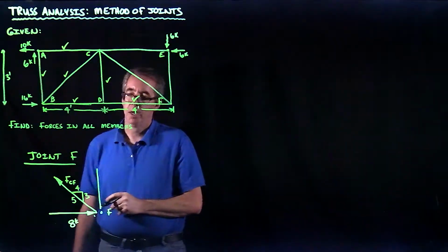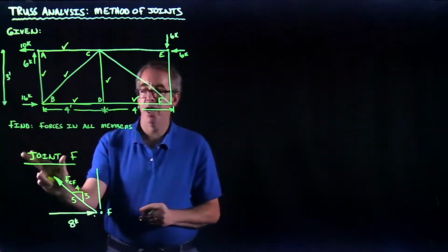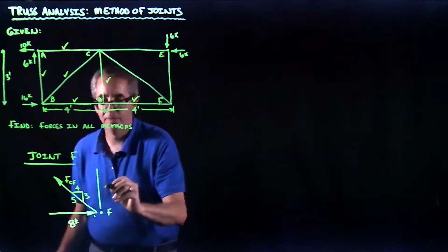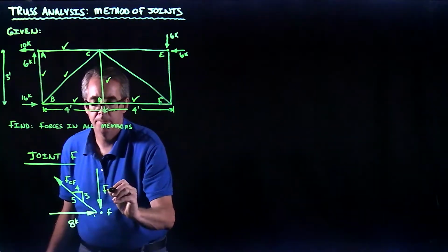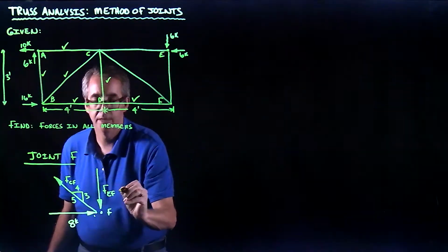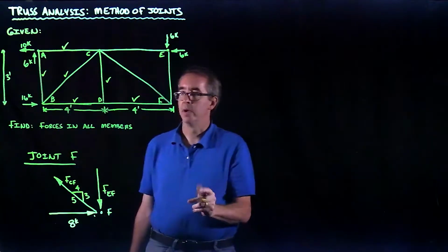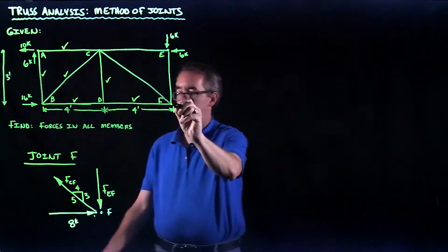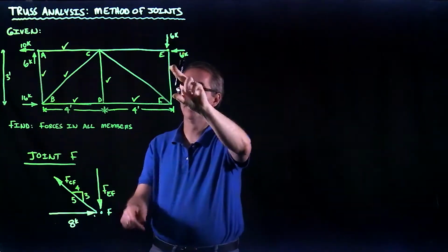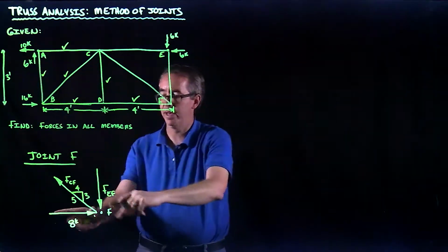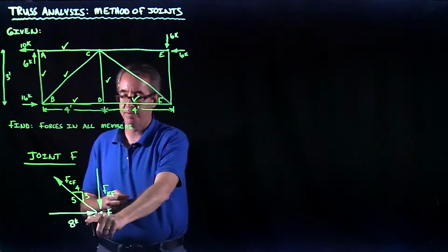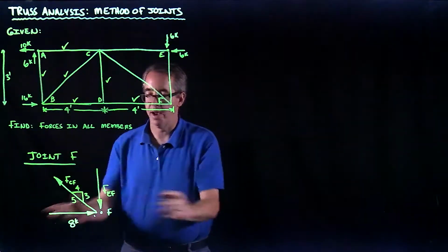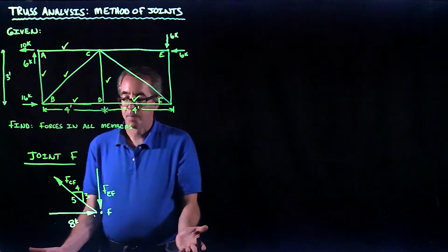All right. Now, if CF is going up, I can see that my force in member EF has to be going down. Okay. So again, I'm looking at joint F here. I've got a force EF here. I've got CF, and I've got DF. DF we had just solved for earlier as having 8 kips. Okay, and now I'm going to just apply equilibrium.